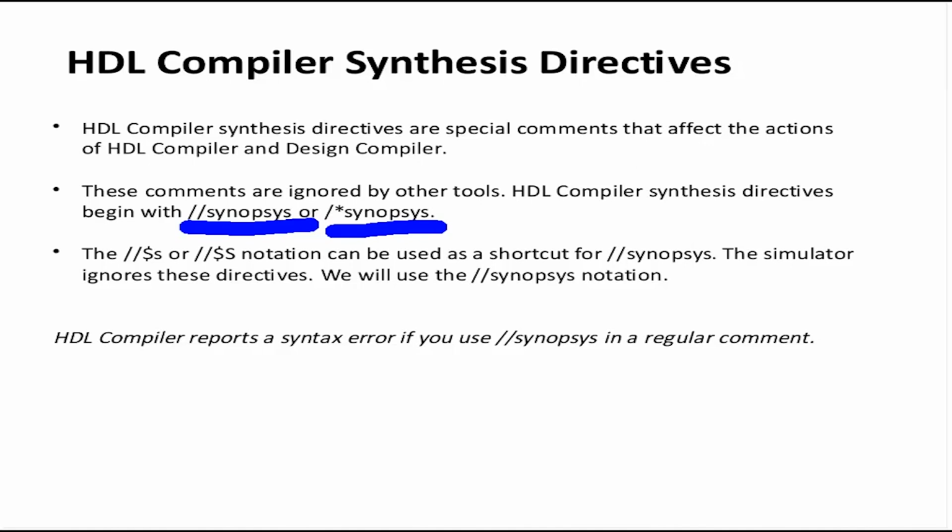They carry special value for Design Compiler. It will modify the way DC reads those statements. It will help you in some cases. These are dangerous in other cases. HDL compiler will report a syntax error if you use // synopsys on a regular comment. We'll see. Now let's look at the few most famous synthesis directives, when to use them, when to avoid them, and so on.